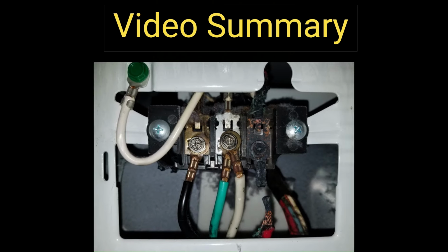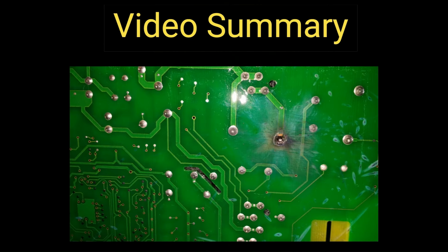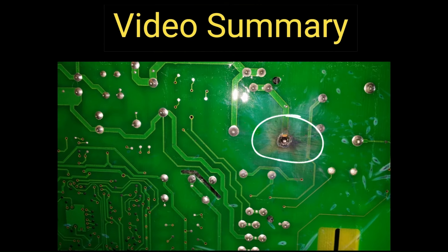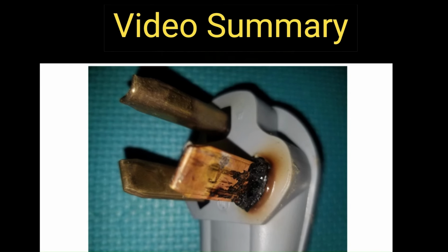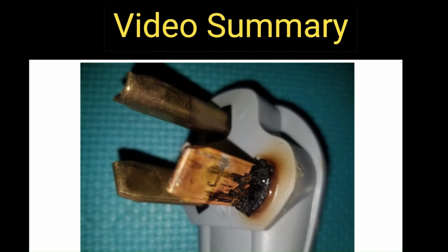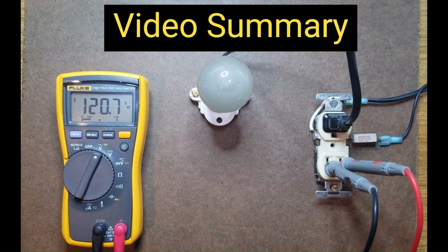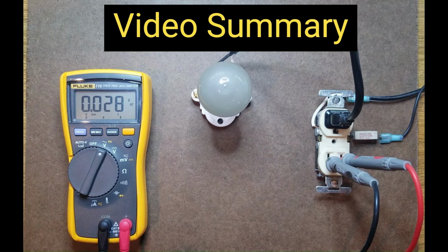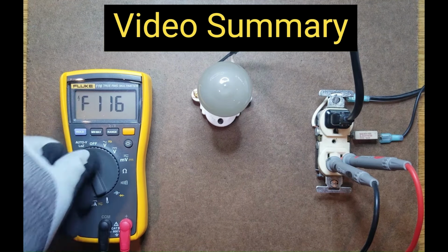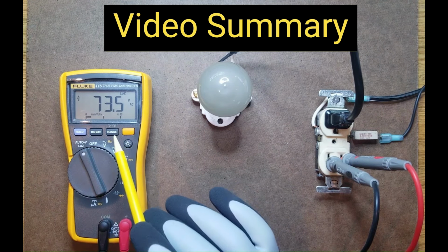Upstream loose connections come in many forms, like this dryer terminal block, this motor relay on a circuit board, and this compromised dryer cord, all of which prevent a load from receiving the amount of voltage needed when drawing its specified amount of current, yet may read a full voltage when measured with a traditional voltmeter. We also learned how we can use the LoZ meter to detect such upstream faults where a traditional voltage reading mode is unable to detect them.